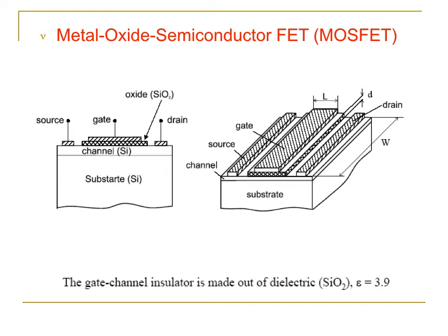This is how a schematic of a MOSFET looks. Here we have a substrate, which is a silicon substrate. Based on that there is the channel base, above which a source, gate and a drain are fixed. There is also an oxide layer, or an insulating layer, between the gate and the channel base. This insulating layer is there just in the gate section. It's not there in the source or the drain, which we can observe in the foremost figure.